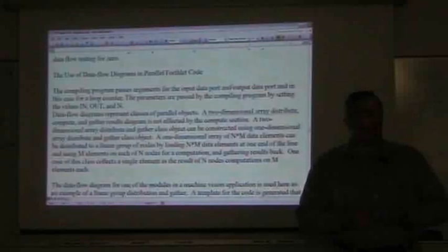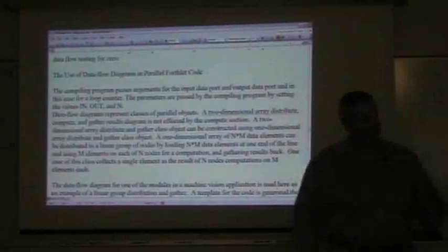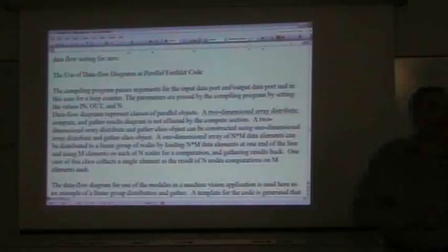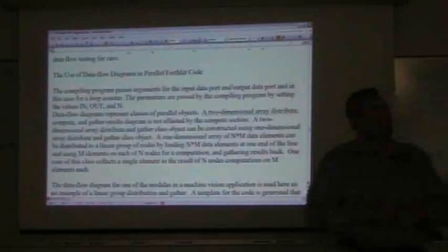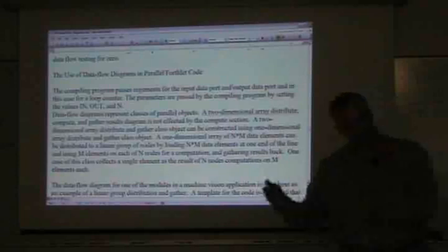And the way this thing worked is it takes pixels from the video image and it brings them in and processes them in a certain way. When the intern originally designed it, the idea was you have to break up a line of video or several lines and bring in the pixels and process them. So what she was doing was to just do it in a very straightforward way. Let's assign 18 pixels to 9 processors and let them perform this algorithm. In fact, let's have 4 groups of 9 processors in each group, which will receive 18 pixels and process them, and then we ship them out.